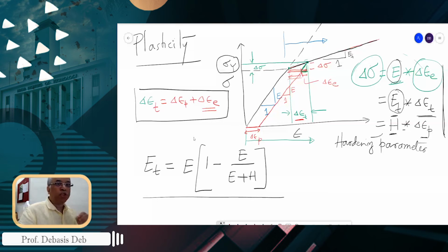Now, the purpose of plastic strain is to change the properties of the material. So, you started with the material which has E, mu, UCS and yield strength. After it fails, its strength will reduce, its modulus of elasticity will reduce. Okay, so it becomes a much softer material.